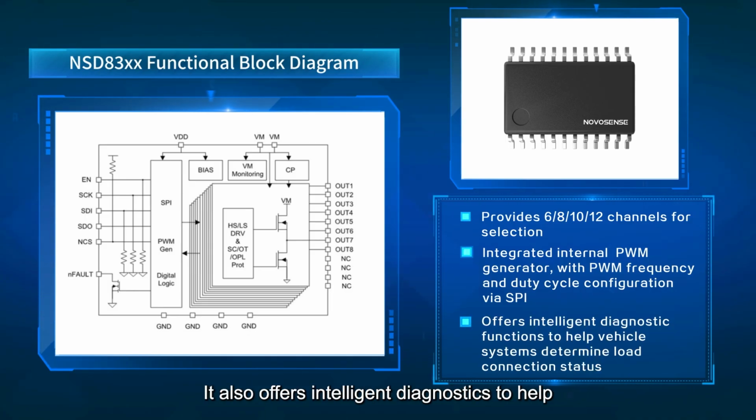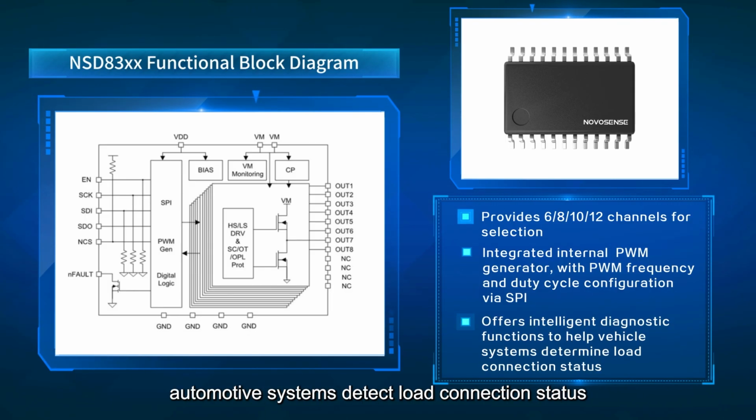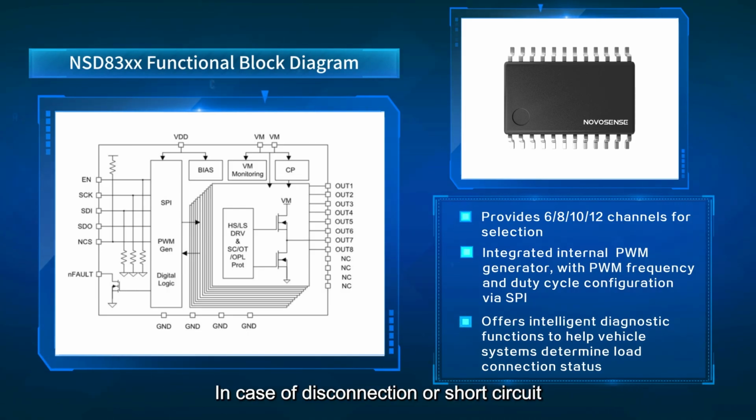It also offers intelligent diagnostics to help automotive systems detect the load connection status. In case of disconnection or short circuit, the external MCU can access channel error info via the chip's internal registers.